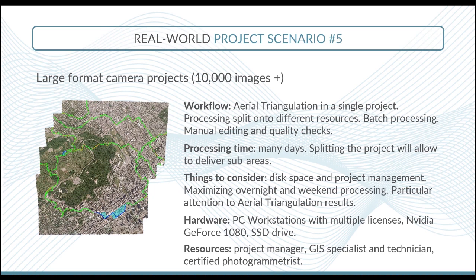For a project like this that may go for weeks, you want to be sure that the aerial triangulation is good, because you don't want to be at the Mosaic stage and just realize that there's a problem in the accuracy in some part of your project, because you have one ground control point that was not good.